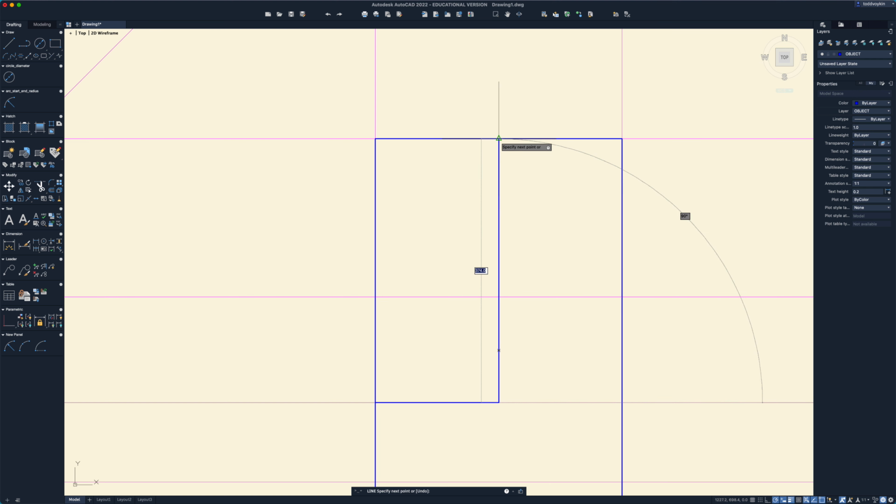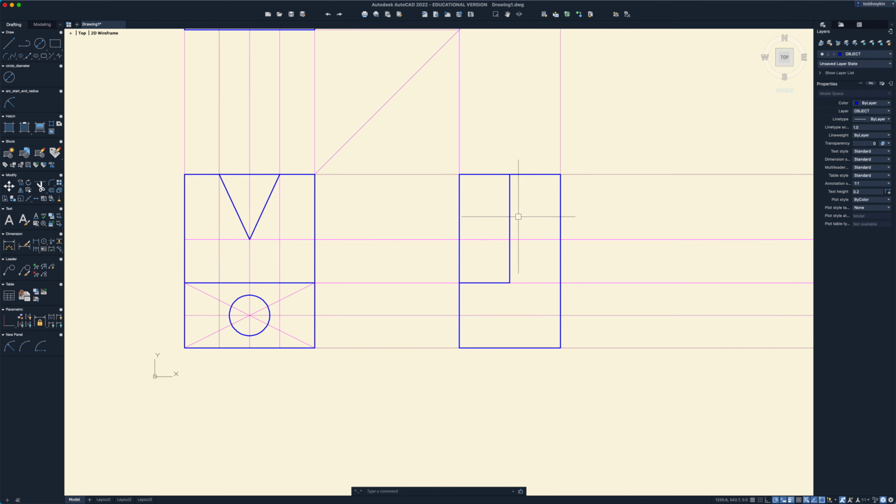Now I'm just going to go up to the top, and it does go to the center point, which would also go to the perpendicular. And what we can actually do if I wanted to go to perpendicular is, before I go to that point, I type the first three letters, P-E-R, and hit enter, and now it's going to find the perpendicular right there, which happens to be at this point the same as the midpoint. So there's our little L, or backwards L shape right there. And this one, where you can see, is the bottom of the V, which will be a hidden line later.